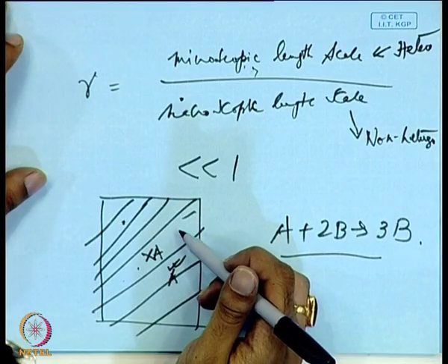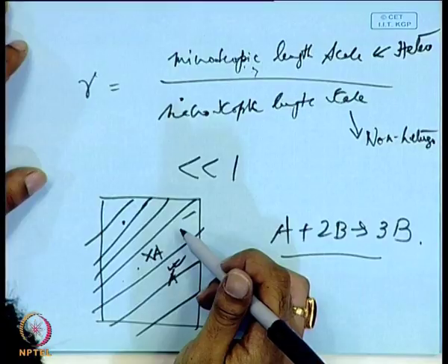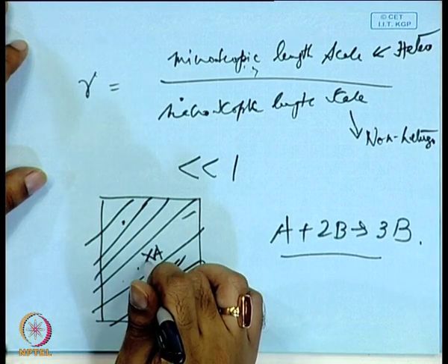No runaway. I am just talking about a catalyst pellet here, there cannot be a runaway in a catalyst pellet. So, this is just a catalyst pellet or an immobilized enzyme, whatever you want to call it. What will happen is that the heterogeneous model is still fine, but you cannot average it anymore. There is no point in having an average when one part has a very large concentration and another part has a very small concentration, because the average value would not give you the right sense of the distribution.